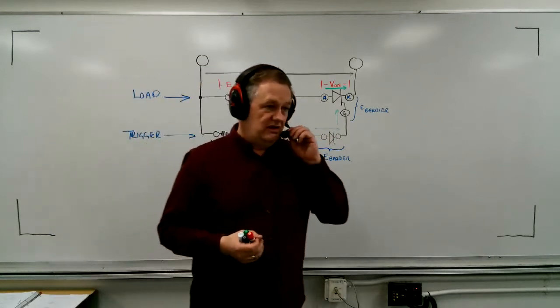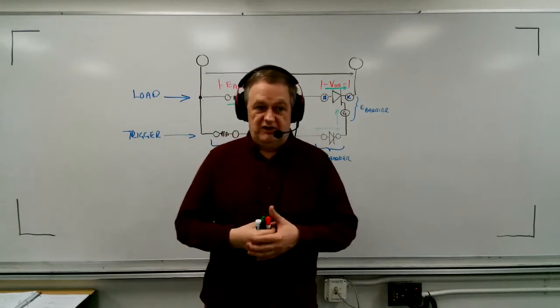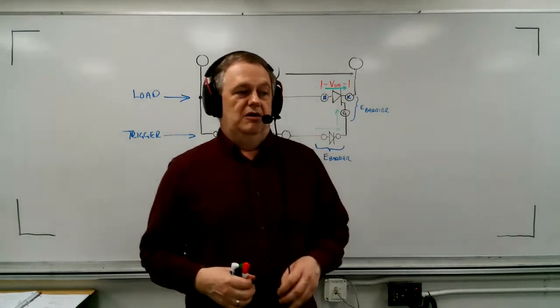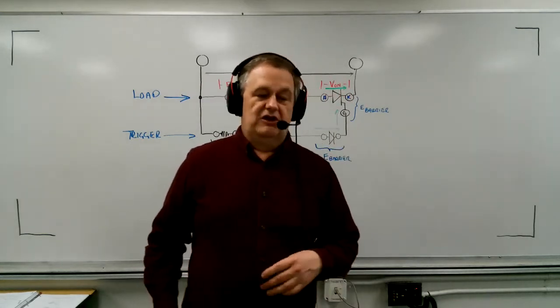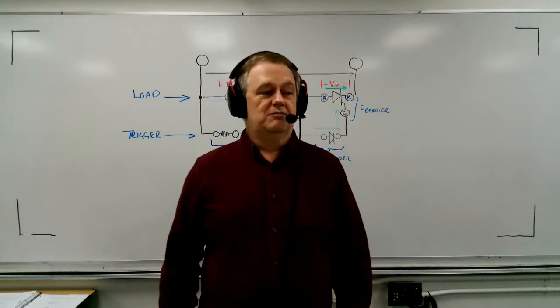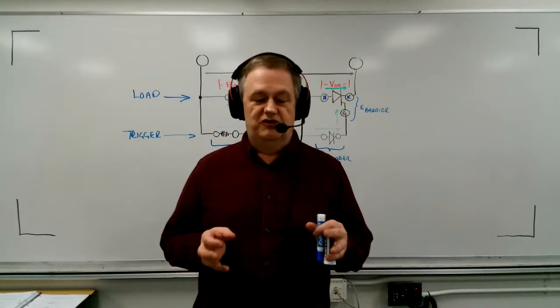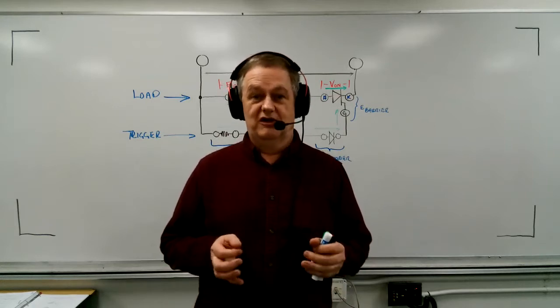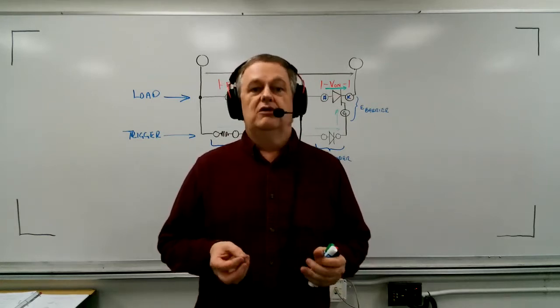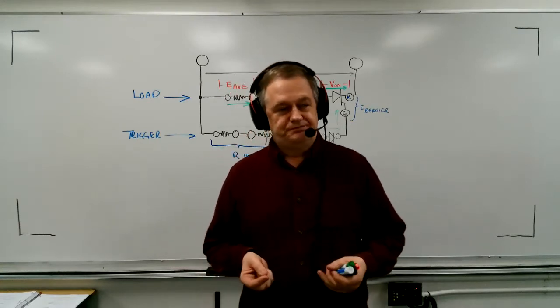So what I want to say is this. Whether you consider the barrier voltage across a diode is something that you need to look at in context. So if we're talking about electronic circuits and you're looking at trigger circuits, for instance, or some other small circuit with low voltages and small currents, then you should count the barrier voltage across the diodes.